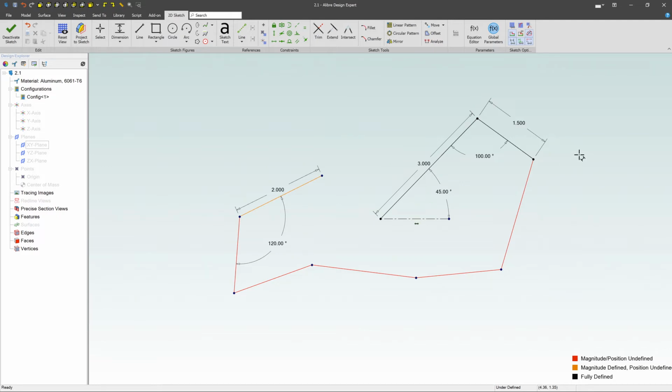Now you can continue going through here. What we're trying to get to at the end of this design is a fully watertight sketch, right? So notice you got a line here, goes around here, around here, around here. Think about it like a swimming pool, right? You have to have one enclosed boundary for it to figure out how to create a solid. So to do that, of course, I got to go back over here to the line, start from that point there, come down here to this point, and boom. Now I've got an enclosed boundary, right?